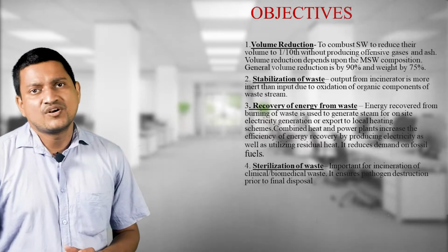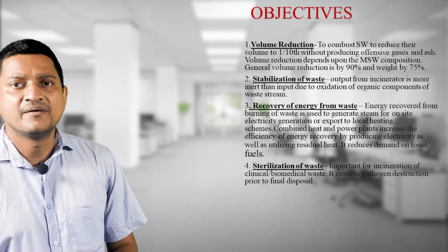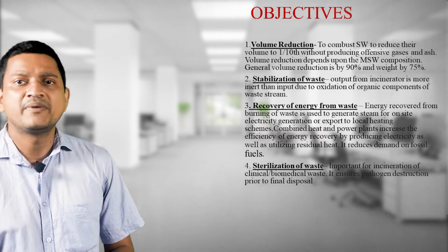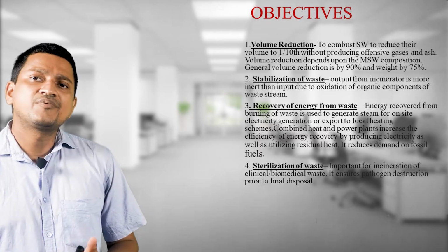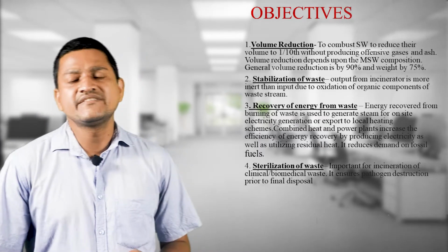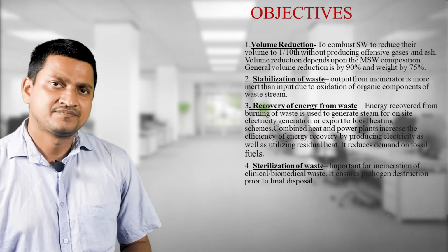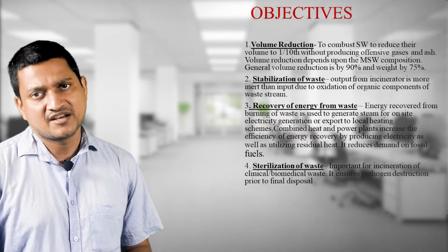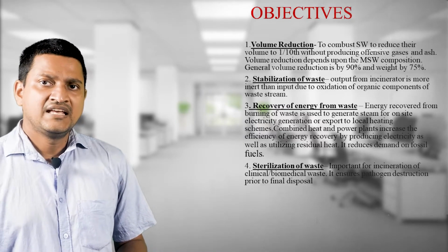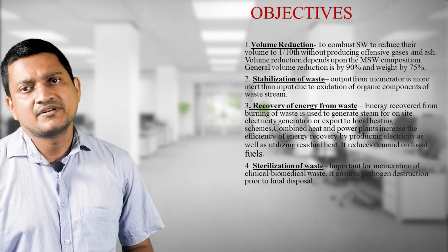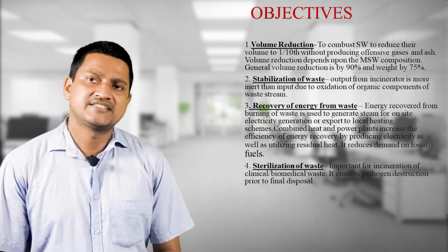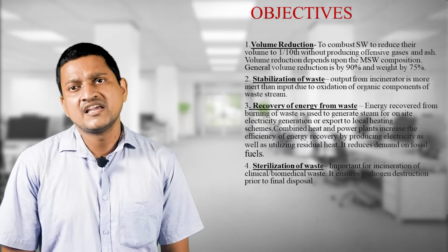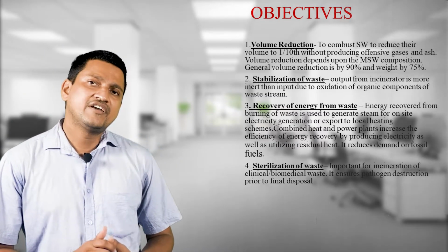It combusts solid waste to reduce its volume to 1/10 without producing offensive gases and ash. Volume reduction depends upon the municipal solid waste composition. General volume reduction is by 90%, and weight by 75%.